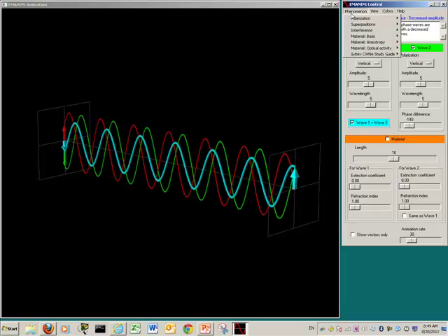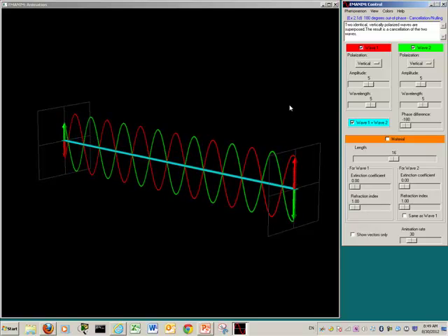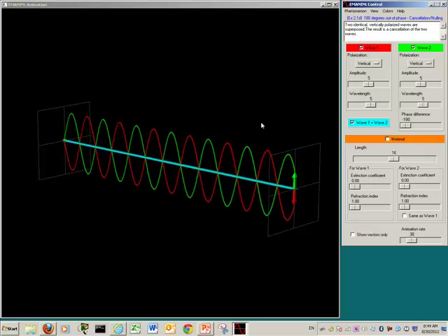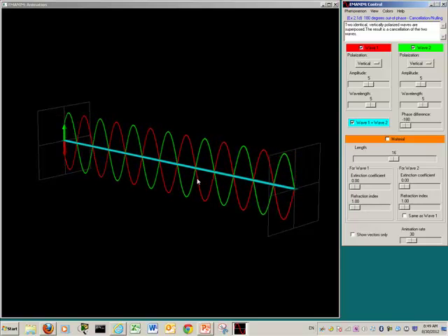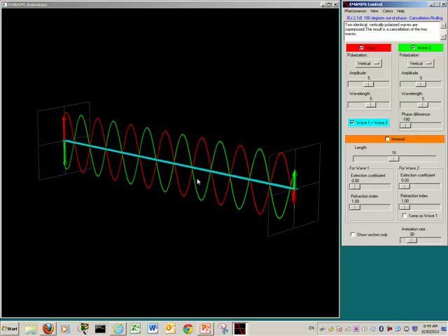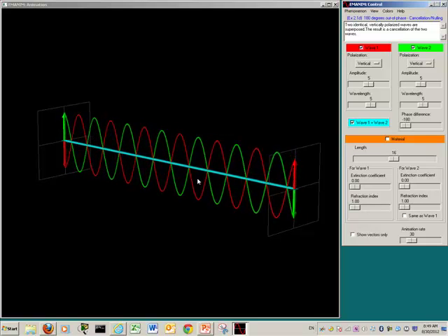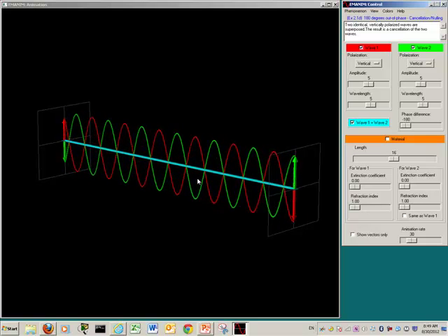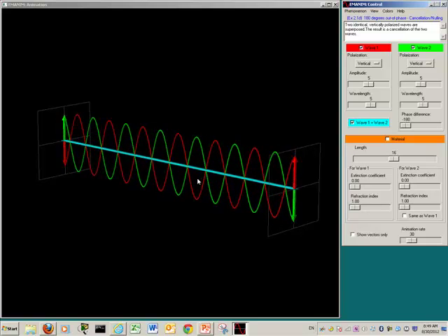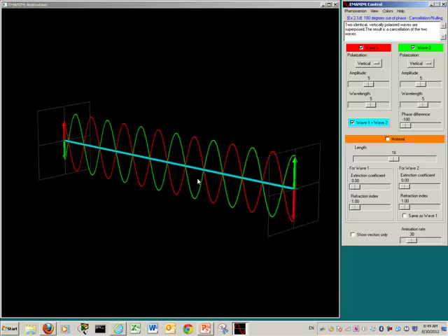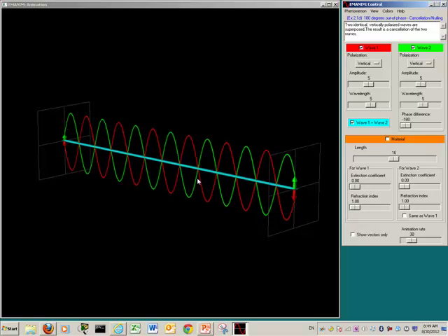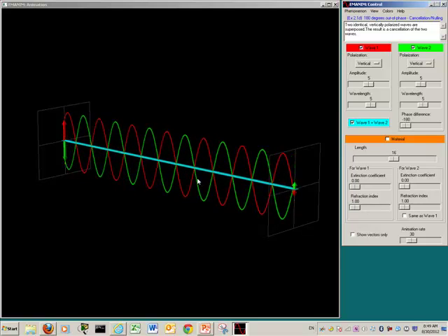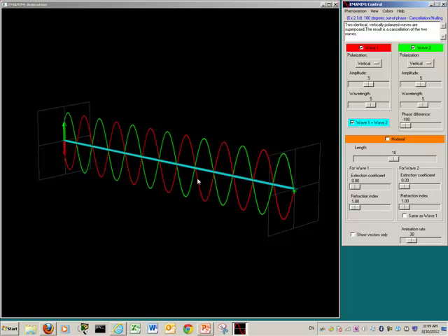And then if we look at 180 degrees out of phase with each other, we still have wave 1 plus wave 2, but they're 180 degrees out of phase with each other, so we get a zero signal. Multipath causes this at the receive end. It is wild, even though you have those signals, if you start them out at the same time, they just cancel each other.